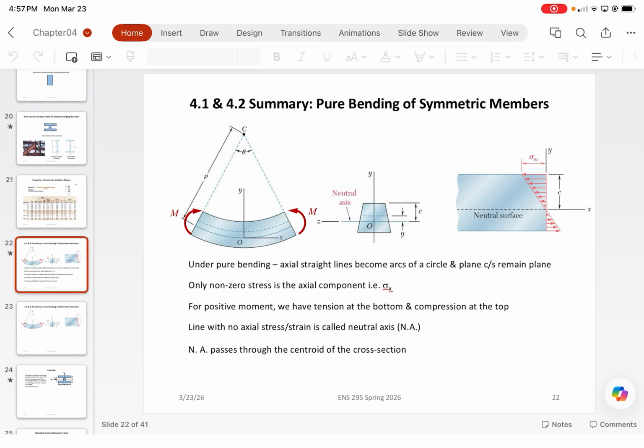So we'll actually get into a little bit of it once we start getting into shear and moment diagrams, which is in chapter 5. So it does become a bit fun once you start getting into the weeds of how to analyze that. But we basically develop what's called shear and moment envelopes, which is basically the worst case loading at any given point.